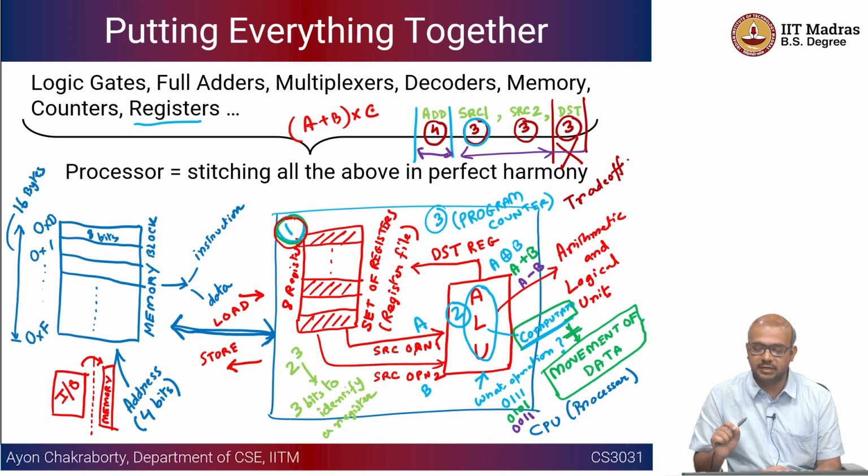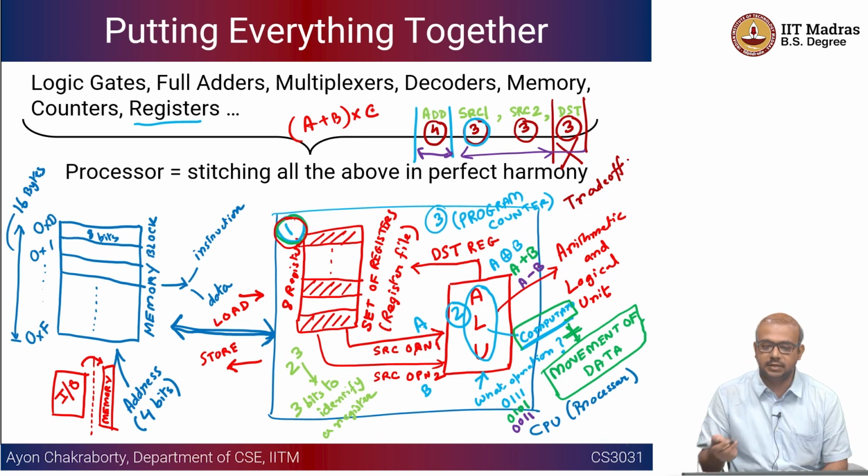This machine language is basically a specific bit pattern that is predetermined by the instruction set architecture. It is going to say that the first 4 bits mean this, the next 4 bits mean this, the last 4 bits mean this. Based on how we design our instruction set architecture, it is predetermined what bits of the encoded machine code instruction mean what. And the processor is going to understand that language and act upon it. We will look at a concrete use case while we design our very simple processor in the rest of this course.